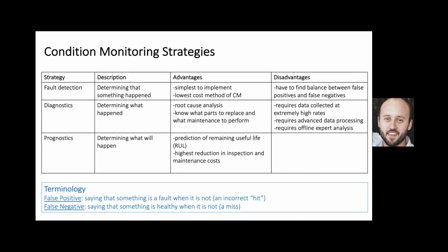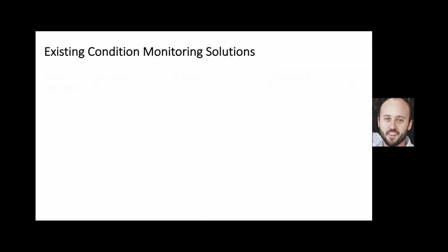So obviously with this approach, we're going to have the highest reduction in inspection and maintenance cost. However, this is in fact going to be the most expensive condition monitoring solution, typically because it's permanently wired, it's constantly collecting data, the sensors and the equipment are much more expensive, and it may need to be coupled with other data streams as well, like maintenance history, failure history, etc.